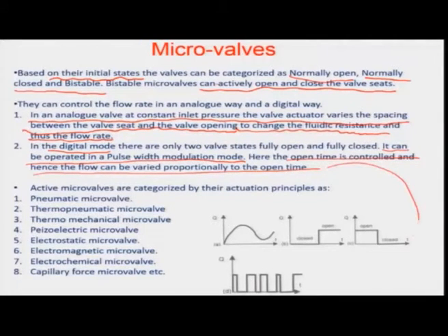So you can see a signal for this kind of microvalve leading to the pulse width modulation activity, where there is a concept of duty cycle where the actuation is taking place, and there is also a part of the cycle where there is no actuation. So really we can optimize this particular pulse width modulation signal so that it is able to respond in terms of fluid delivery by opening and closing at different frequencies and different lengths of time.